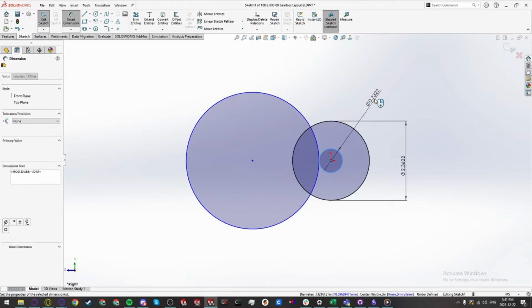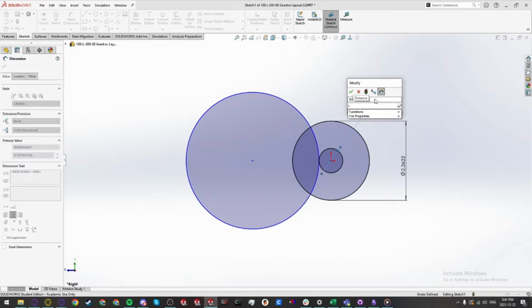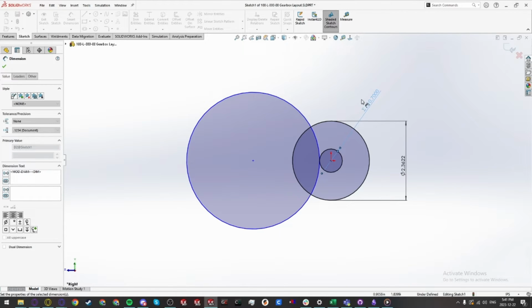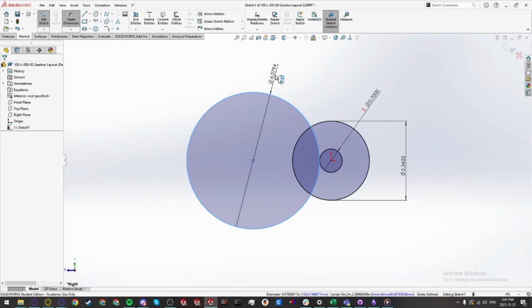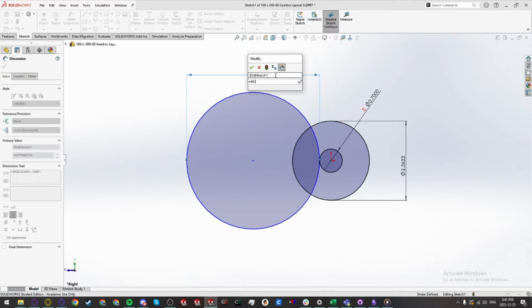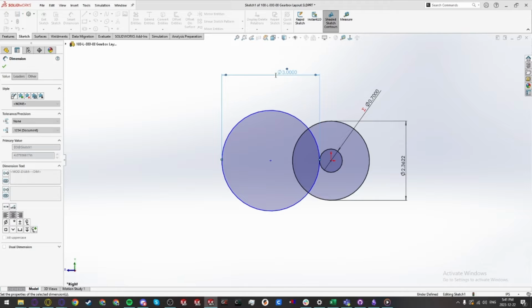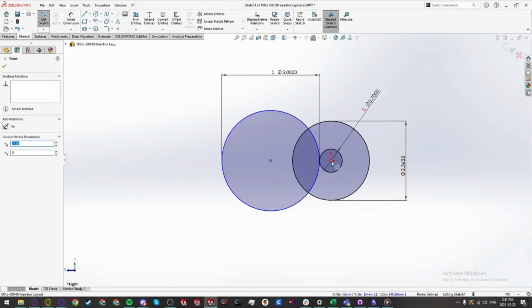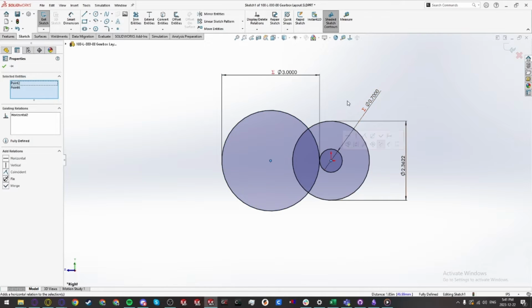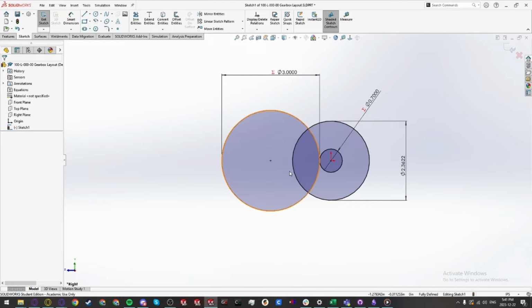The motor pinion, I know it's going to be 14 tooth and 20 dp, so I'm going to make that 40 divided by 20. I use the equal sign there so that when I am done calculating this value, I can still double click and edit it very easily. And over here, the connecting gear is going to be a 60 tooth 20 dp gear. Just to define this, I'm going to make this horizontal. And so that's our entire gear train.